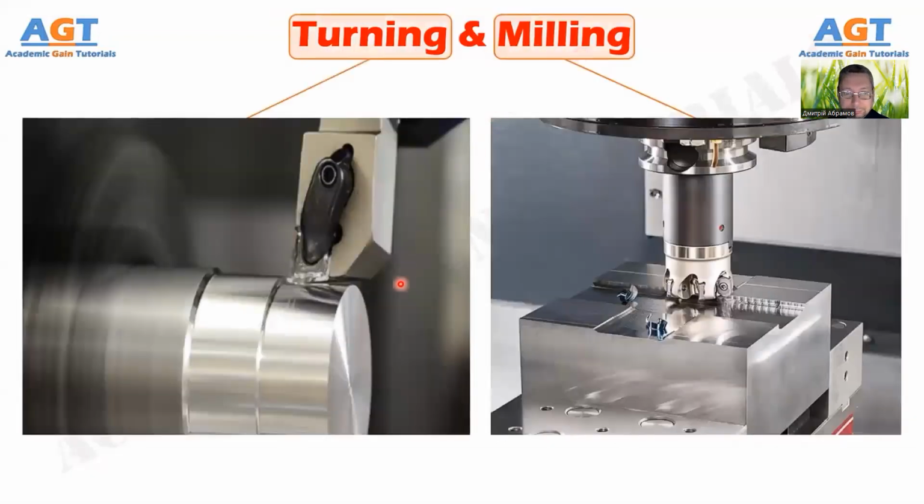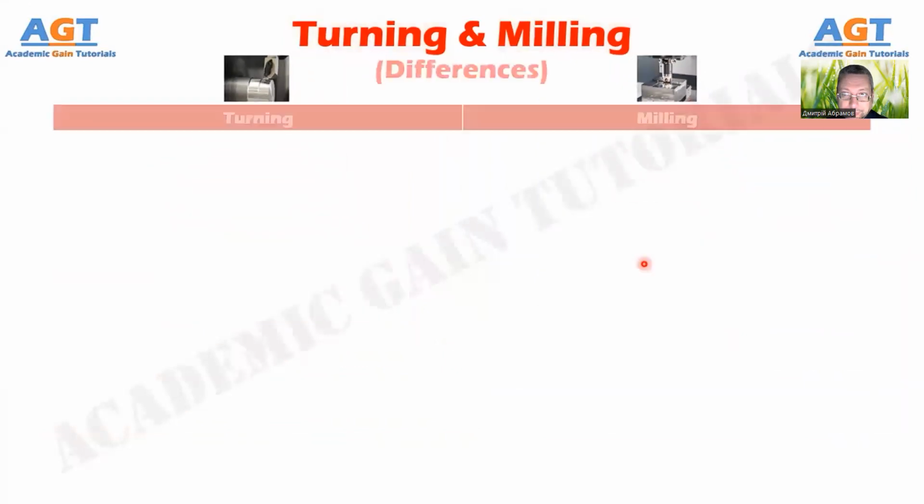Conventional machining is one type of manufacturing process in which excess material is removed from a preformed blank by shearing in the form of chips using a wedge-shaped cutting tool in order to get the desired shape, finish, and tolerance. There exist several machining processes to efficiently machine a wide variety of materials in innumerable ways. Turning and milling are just two examples of such machining processes. So, let's look into the basic differences between turning and milling processes in a tabular form.